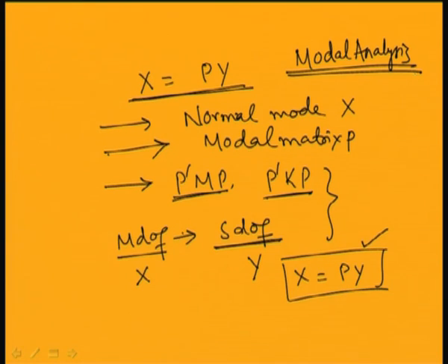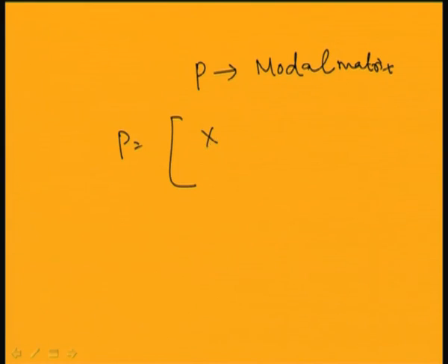Also, you can simplify this by using another matrix that is known as the weighted modal matrix. The weighted modal matrix can be obtained from the modal matrix. Let the modal matrix be P. The weighted modal matrix can be obtained by dividing the columns; let the P matrix equal x1, x2, x3 for a 3 degree of freedom system, and let M1, M2, M3 be the generalized masses.